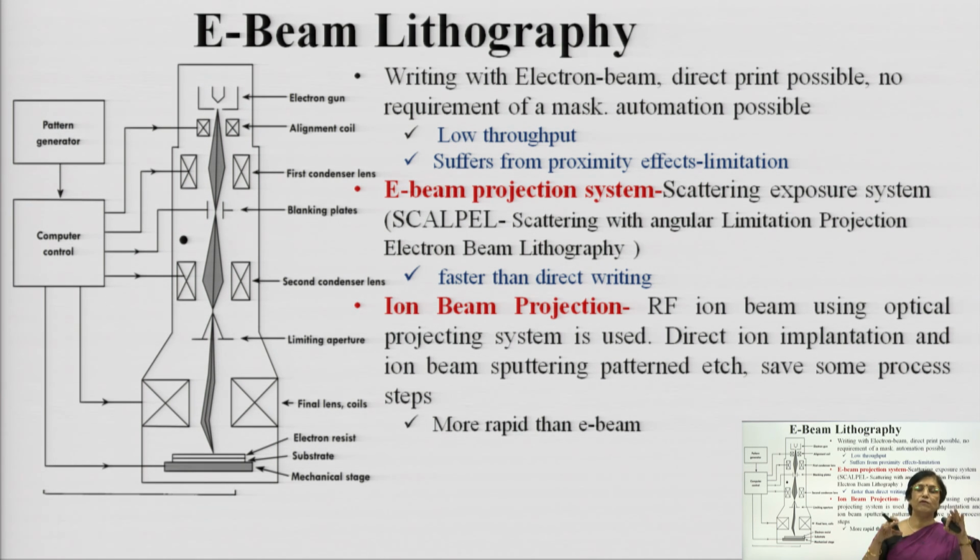Suitably you have to make use of those photoresists, and the choice of photoresist is very important when you are considering throughput. Naturally, positive photoresist is expensive and a time consuming process, whereas negative photoresist will reduce the throughput because of the swelling and resolution. So both resists have pluses and minuses.